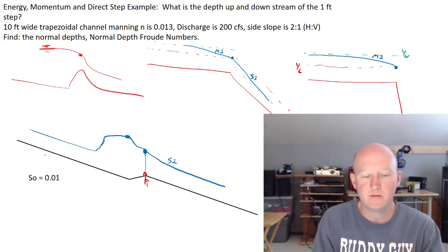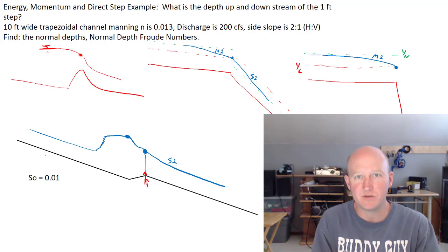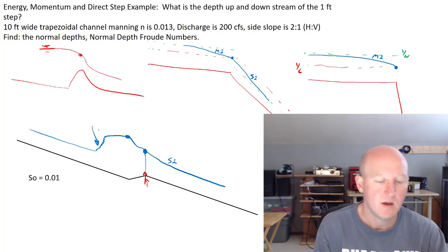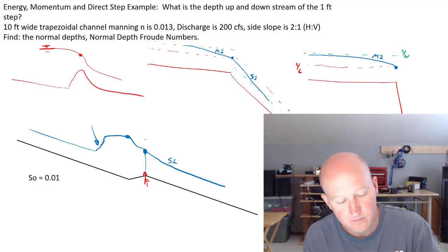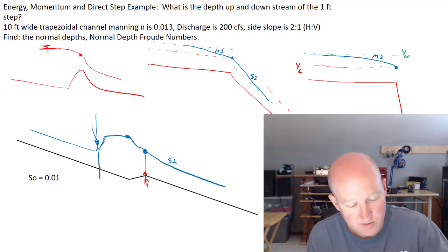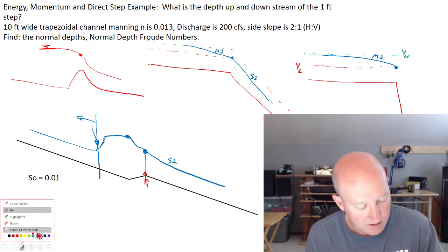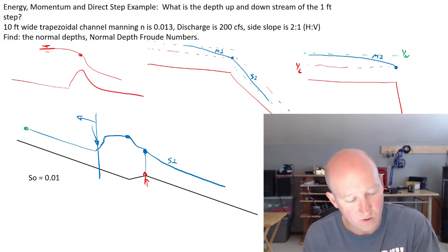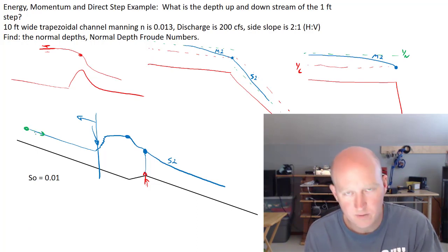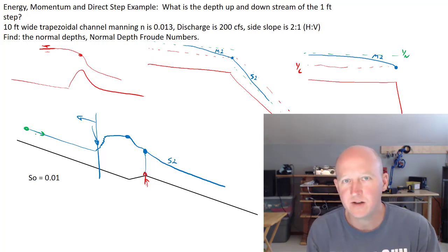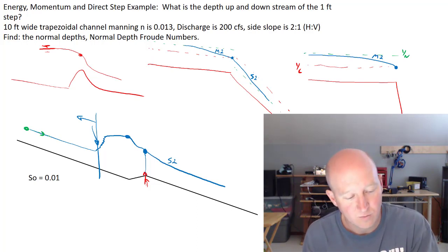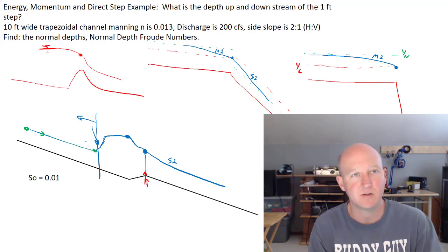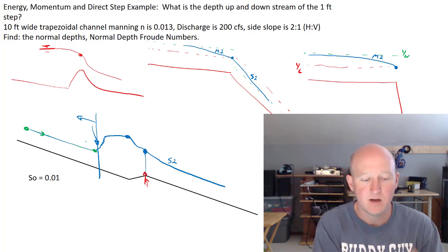So the other thing to keep in mind is that it's sometimes, especially for people that are new to this, like, why does there have to be a hydraulic jump right here? All right, so the idea is basically that from this point upstream, everything is upstream controls. And so what that means is that the water is coming downhill. If you imagine being a piece of water, you're racing downhill, and it's almost like you just can't see what's going on in front of you until you smack into this hydraulic jump, and that's because a wave cannot propagate upstream.